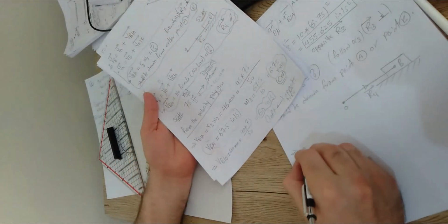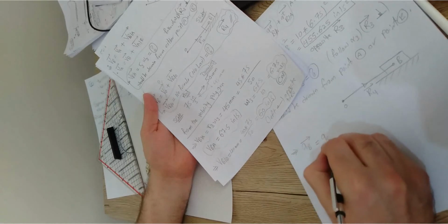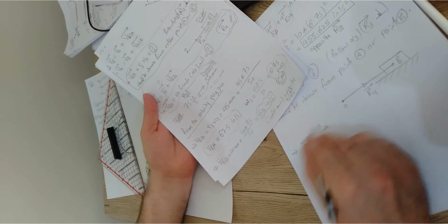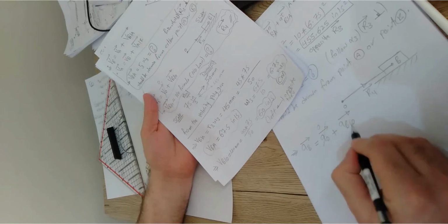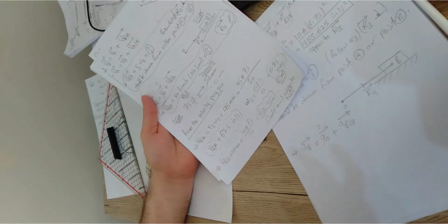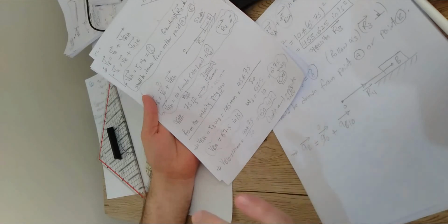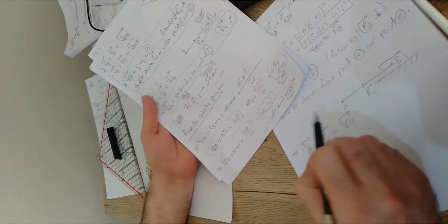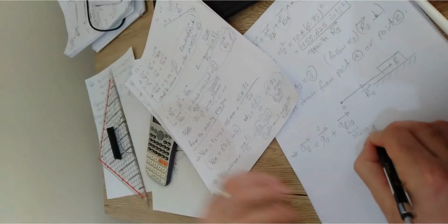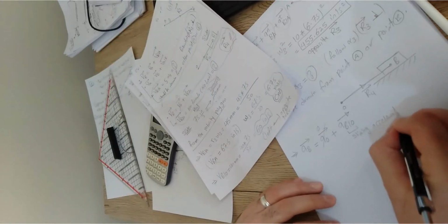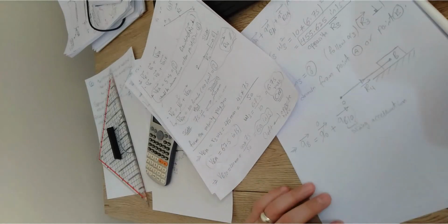So it means that we're going to have the acceleration of point A vector equals the acceleration of point O vector, which should be 0, plus the acceleration of point A relative to O vector, and here we end up with just one relative component, or one component of the relative acceleration of point B with respect to O, which should be the sliding acceleration of this slider. Make sense? And this is the thing that we have to draw.